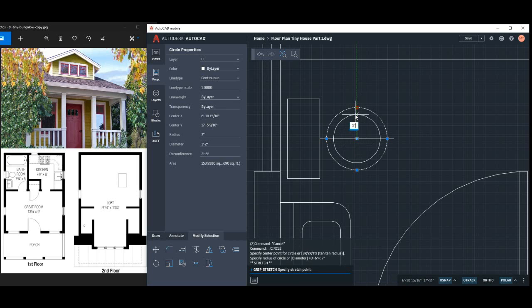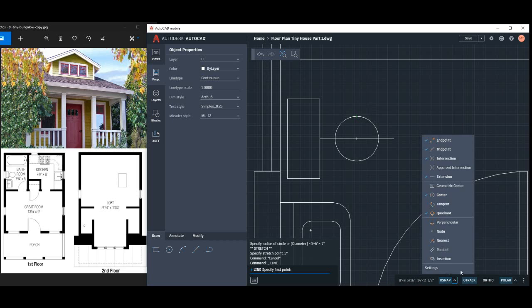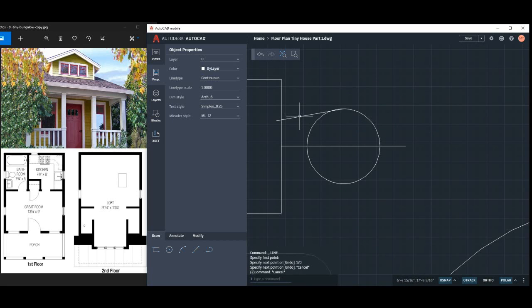That's a little bit big, so I'm just going to shrink it down. Let's go maybe 5. Better. Now I'm going to use the line tool and an object snap called quadrant right here. What you do is you turn that on, you click here, point to the tank here. I'm going to press Tab, type 170 for the degree of the angle.